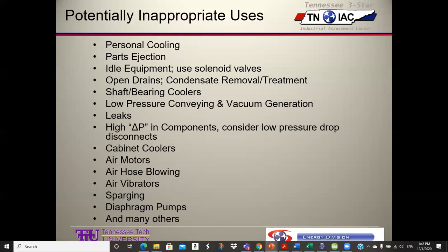So what that means is sometimes we'll have a nice big compressed air distribution line, and we'll come off of it with a 1/2 inch line or even less than that going to a use, and we have a huge pressure drop across that last little piece of line, which then causes us to jack up the compressor pressure. Whereas if we put in a 1 inch line instead of a 1/2 inch line, which wouldn't cost very much in most cases, then we could lower the compressed air pressure, or certainly not raise it, and save a considerable amount of energy.